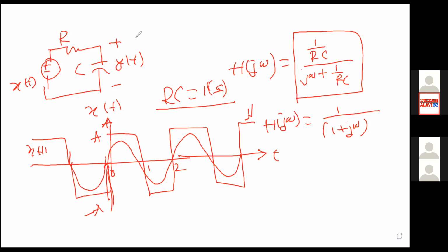Okay, we have a simple machine there by which you can analyze your Fourier series. Even nowadays, an oscilloscope can also generate your Fourier harmonics, so you can easily identify what Fourier components are present in your system. It is very simple. For example, if you want to learn how many frequencies are there in your signal, you can give x(t) as an input to a system, say this is a tunable filter whose frequency can be tuned, and we have our output y(t). Then what will happen?